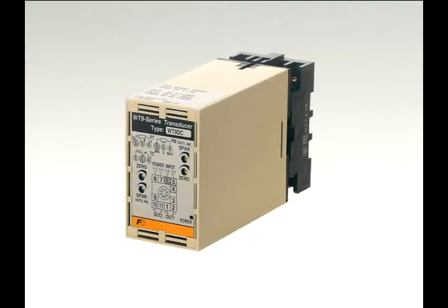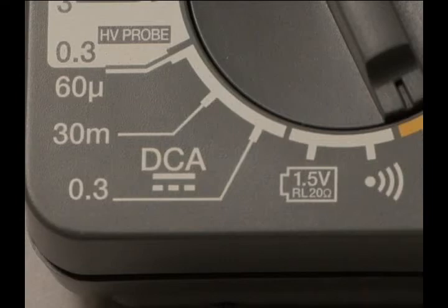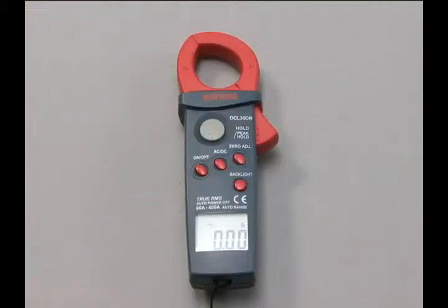Frequently, a weak signal from the sensor is input in a transducer and then converted into an electrical signal of between 4 mA and 20 mA. A tester to verify the operation of the sensor and transducer can be used to measure a weak current, but not a heavy current like the one flowing through a motor. For a heavy current, a clamp meter should be used.